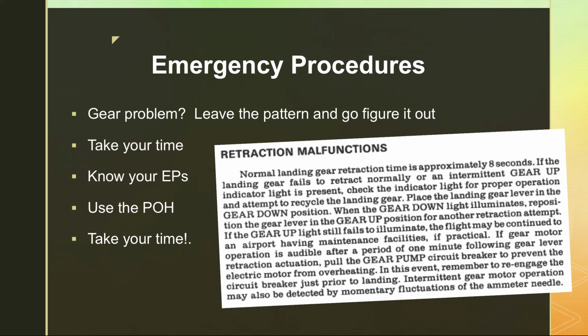But a few things: know your aircraft before you fly that aircraft. In the air, when you have a gear malfunction problem, is the wrong time to start reading what to do if you have a gear malfunction. Take your time. You probably have more than enough fuel for this. What you don't want to do is land with the gear up after you've thought you've exhausted all your other options, and then slap yourself in the forehead and say, oh, I guess I probably should have checked the circuit breaker, which has also happened.